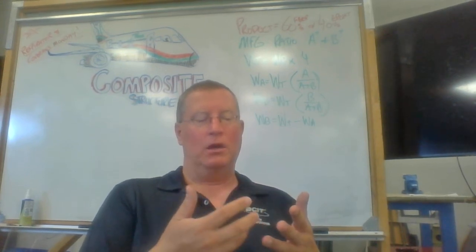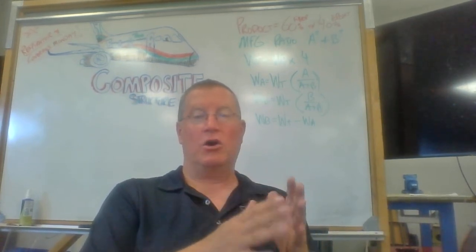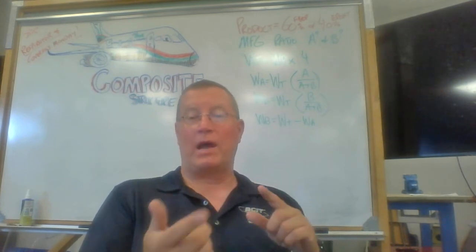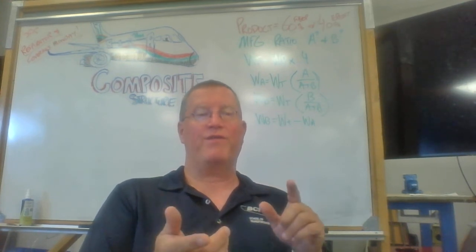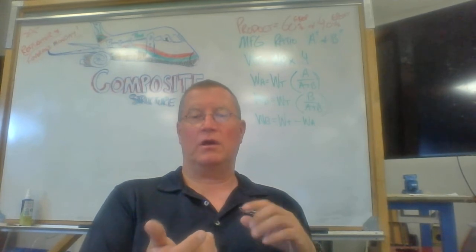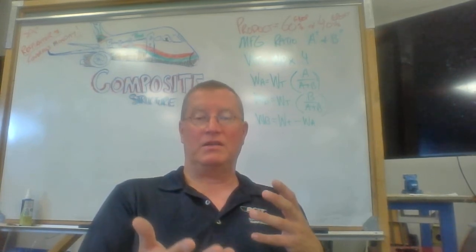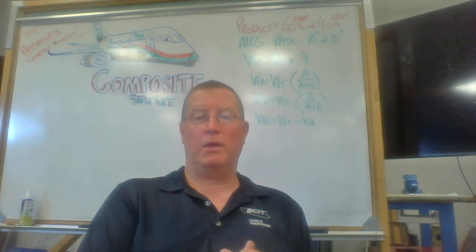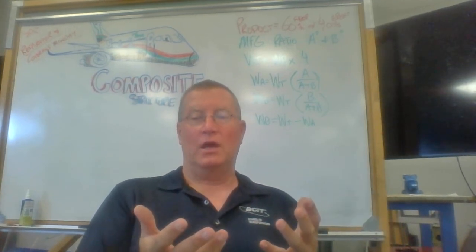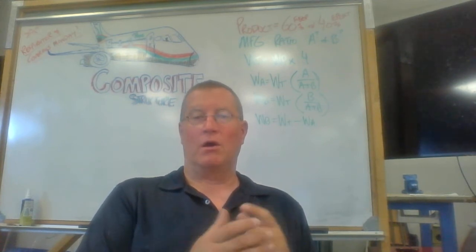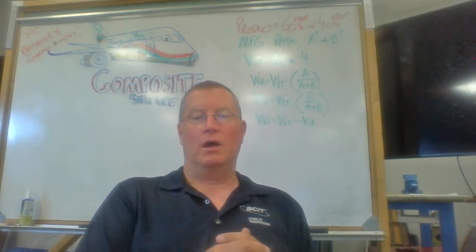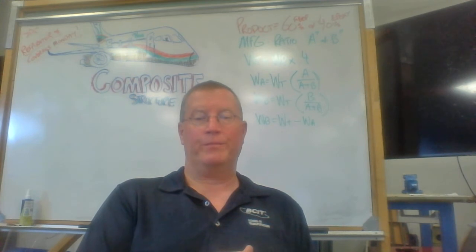So if it's a metal fiber, we've got to make sure that it's in contact with the other metal fiber, and then somehow after the fact we'd have to go and do some sort of a conductivity test, verifying that the repair material is in contact with the base metallic material, and so you'd use something like an ohm meter. And then the other thing we have to be careful of, of course, is chemicals. Not so much for the fiber, but the matrix. And so we want to be careful with the use of nasty chemicals around our exposed composite material with the potential of softening if they come in contact, right? So something we have to keep an eye on.